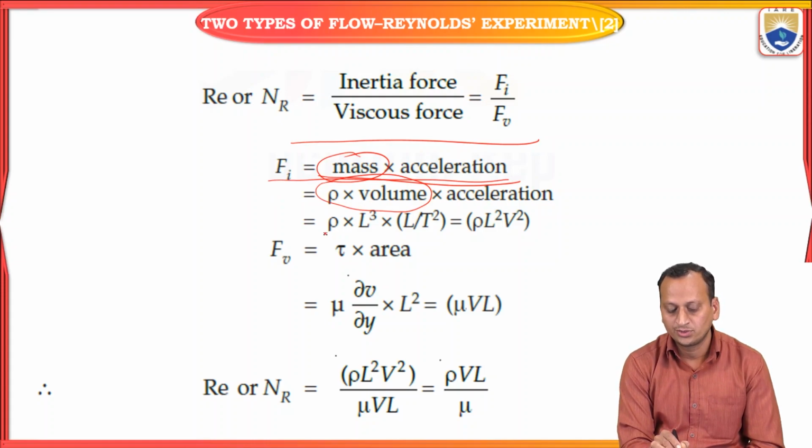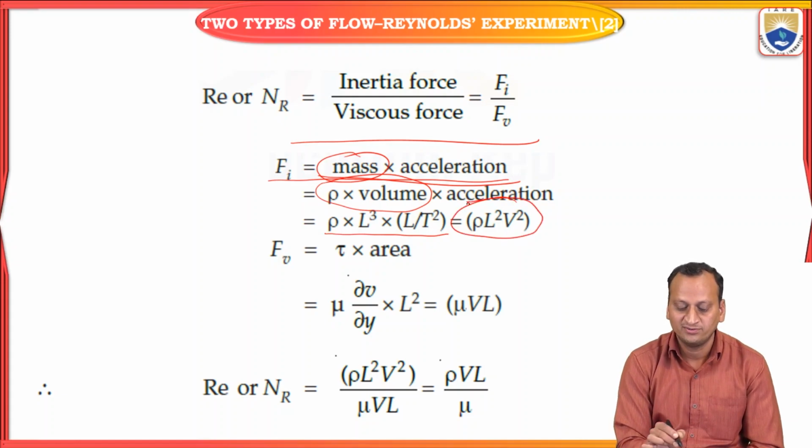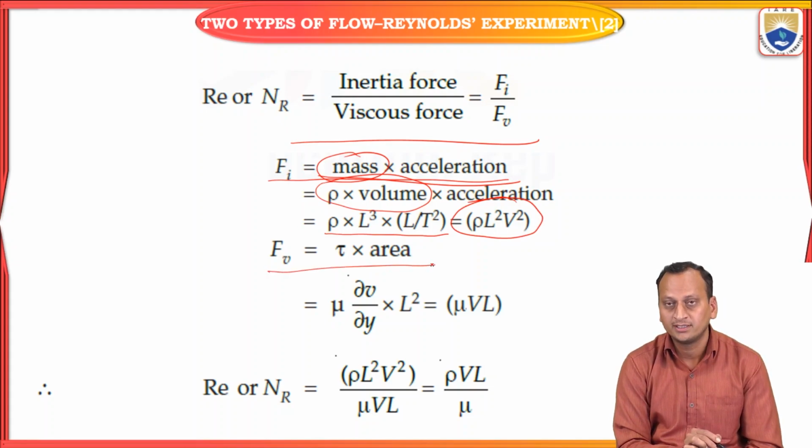So this includes rho L cube into L by T square, otherwise rho L square V square. This is the dimension of inertia forces. Inertia force. A viscous force is nothing but shear stress into area.